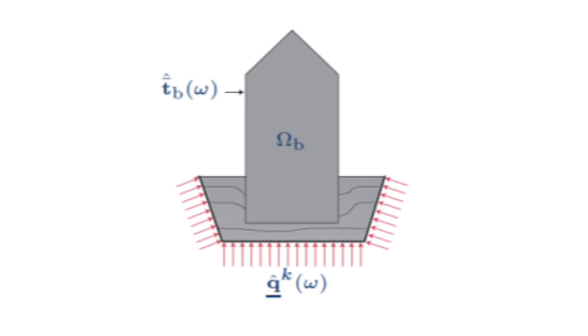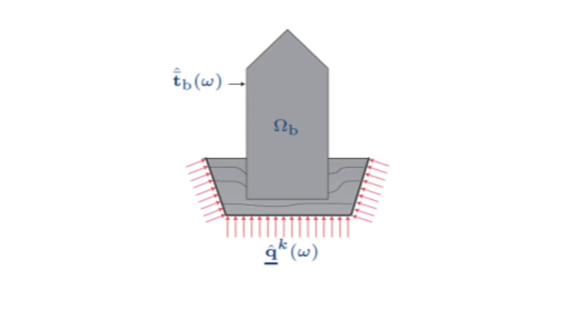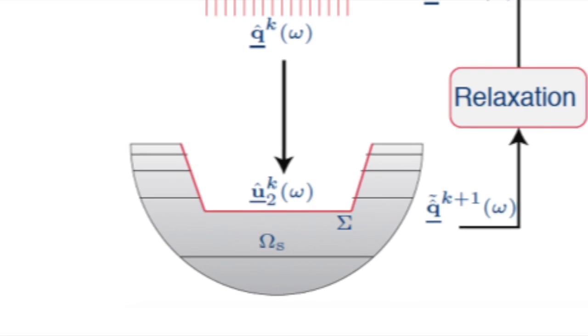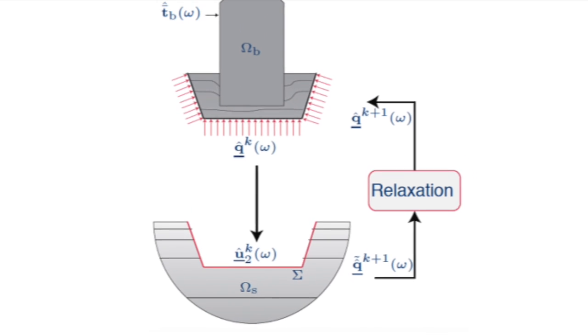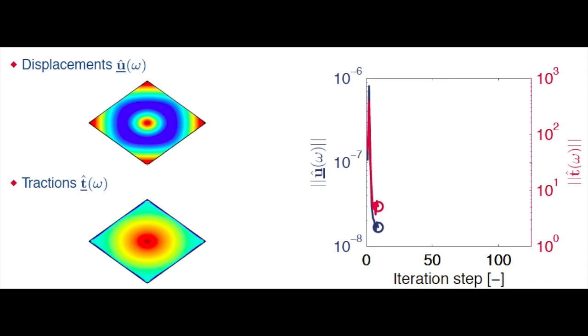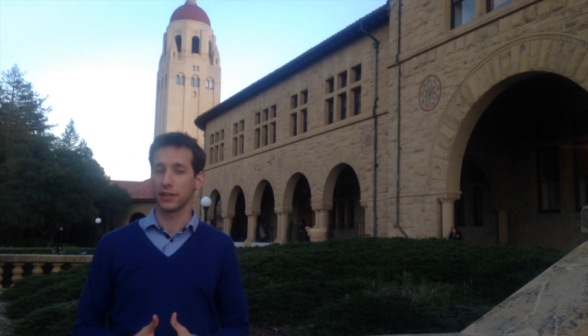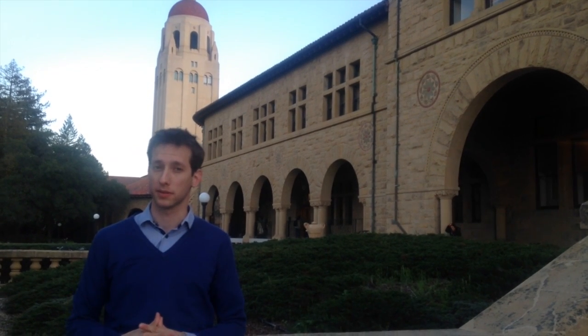Apart from speeding up the boundary element calculations, Pieter has also developed techniques for a more efficient coupling of finite and boundary elements. He has focused on iterative coupling algorithms, in which the governing equations are solved separately for each subdomain, while the displacements and stresses at the soil structure interface are updated until convergence is achieved. These iterative algorithms are significantly more efficient than classical coupling approaches. The developed methodologies provide an efficient solution to large three-dimensional dynamic soil structure interaction problems.